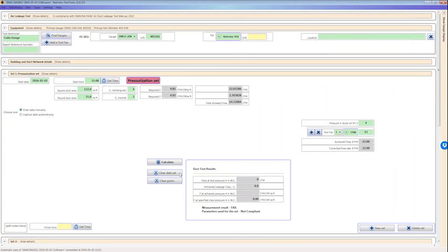The other thing I wanted to mention was that one of the guys at the NEB show was talking about attaching a whole bunch of flux ducts onto the duct system, and then going around with the duct tester and attaching it to each flux duct in sequence. There's actually a much easier way to do that, and that's to buy this thing that we call a Lindab collar. It's a round 4-inch collar that you can screw onto the duct. You can leave it there permanently. It only sticks up about 2 inches max. And there's a cap that goes over that seals it off 100%.